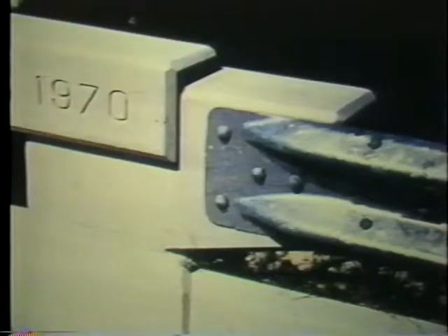The end anchorage at this concrete bridge rail was not strong enough to provide continuity of beam strength from the W-beam to the bridge rail. As a result, the W-beam tore loose at the connection, and good connections to the bridge rail are always necessary. To get a stronger connection, drilling completely through the concrete section and using a steel backup plate or heavy washers would provide good anchorage. Here you can see a transition connected correctly.